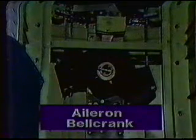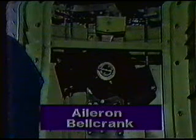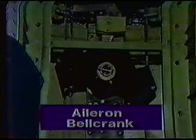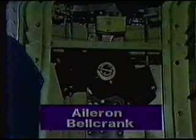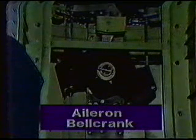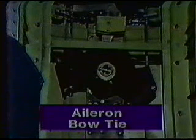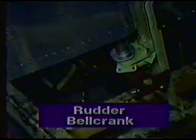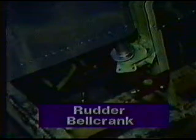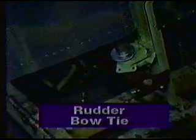Several bell cranks are used in the flight control system. There is no precise definition as to what the difference is between a bow tie and a bell crank. As such, the unit located midway in the fuselage is either called the aileron bell crank or aileron bow tie because of its shape. The unit to which the rudder control cables attach to the rudder is the rudder bell crank or rudder bow tie.